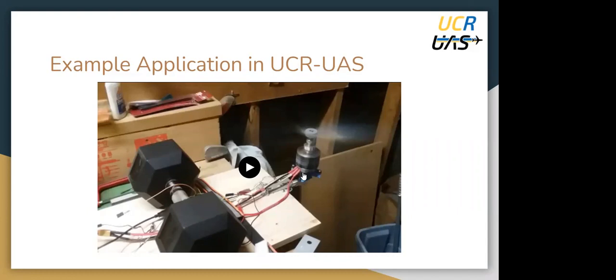When we are testing motors, we have a load cell that is measuring the thrust that the motor produces because it's got a propeller fixed to it, and then another sensor that can allow us to record the RPM. You can't see the Arduino because it's hidden here, but it's hooked up to these two sensors and recording data in real time.